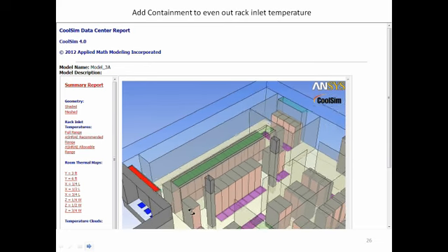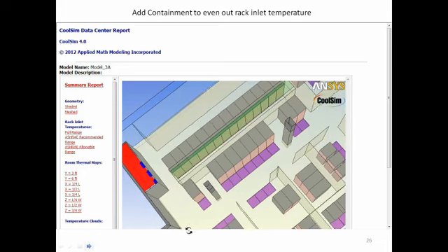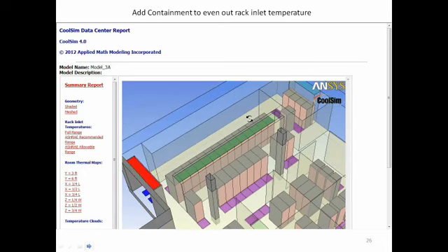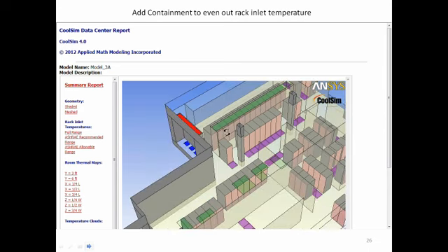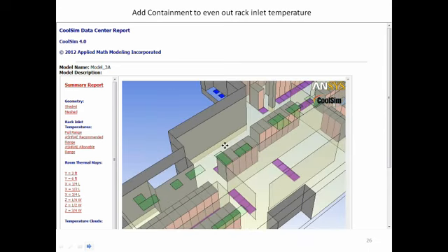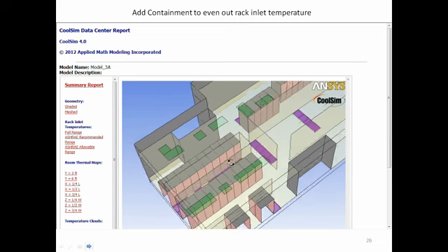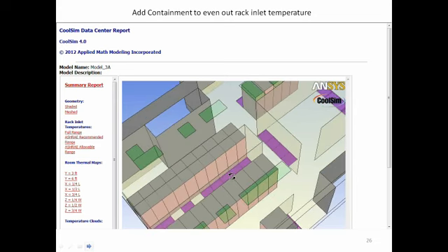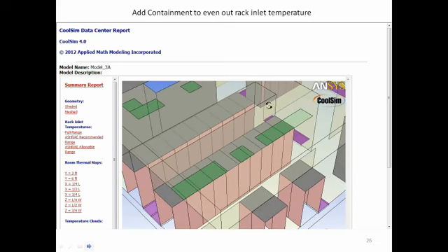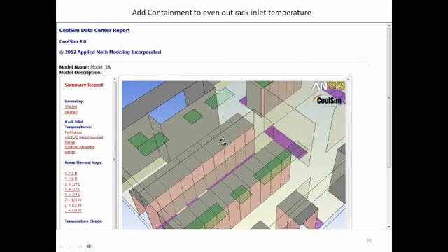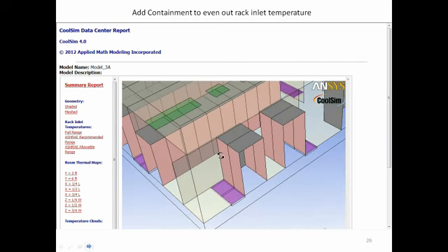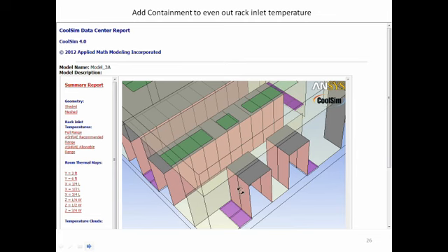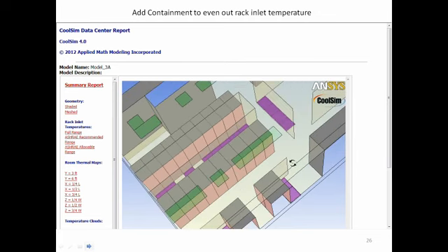To get that distribution of temperature a little more even than what we were just looking at, we can box in this region right here, and you see I've started to do that with these baffles. And also I've blocked in between the servers here. These are typically in the room what you put is curtains. Here what we're using is simple baffles to do this. Now down here at this end of the room, I did a little bit of work with cold aisle containment. Here we boxed in the racks, put a curtain across the top, across the end. This is a cold aisle, and I'm trying to preserve the coolness down there. And also in these corners I put a sheet across and put a little edge here on this side of the room.